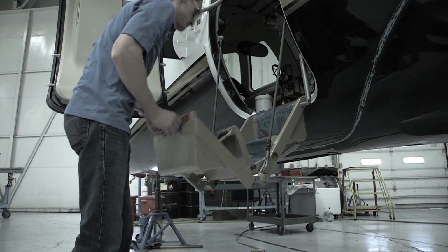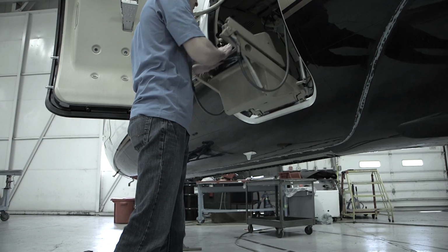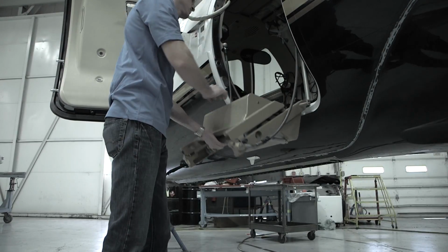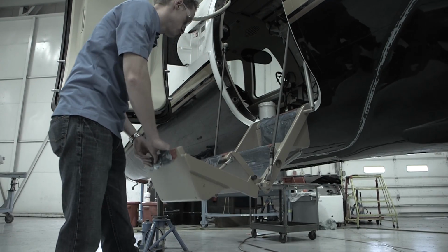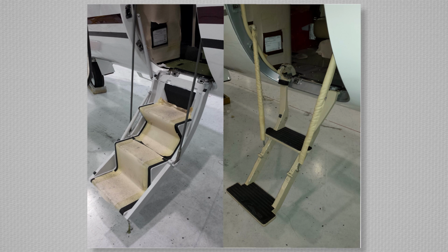As your aircraft ages, the main cabin door entry steps will take thousands of up and down cycles between aircraft operation and maintenance. If you operate a Model 500 series aircraft, your aircraft is configured with either of the main cabin door entry steps shown here. These steps contain small bearings at the upper, forward, and aft fittings that can wear and become elongated as years go by operating your aircraft.